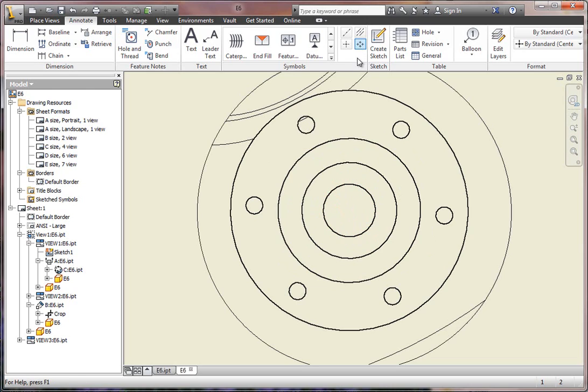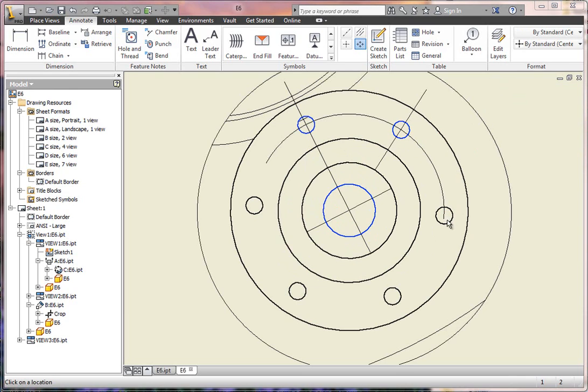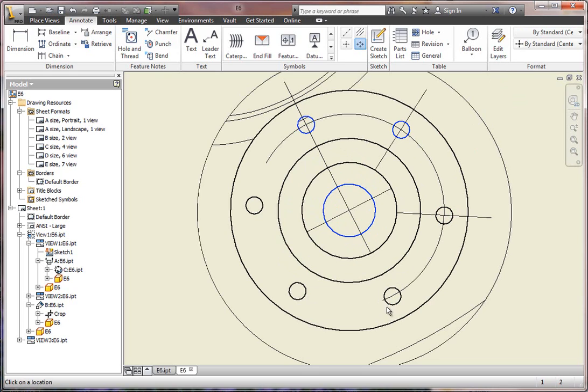After you select centered pattern, select the inner edge, and then go ahead and select every center point, and it will continue on until it's done. Then once you have that completed, you'll have to right mouse button click and hit Create, and it will create the bolt pattern.